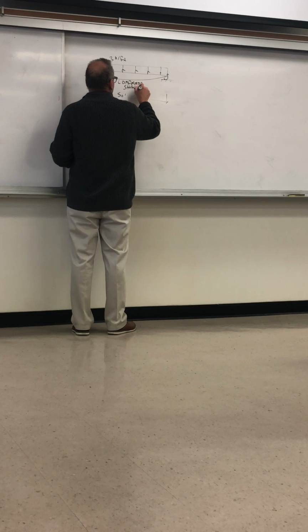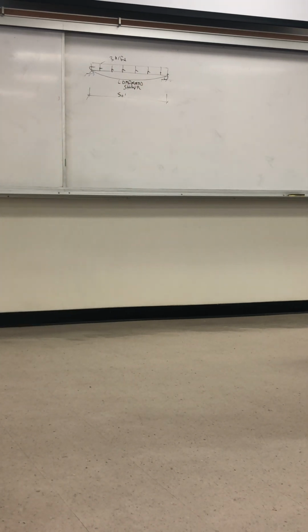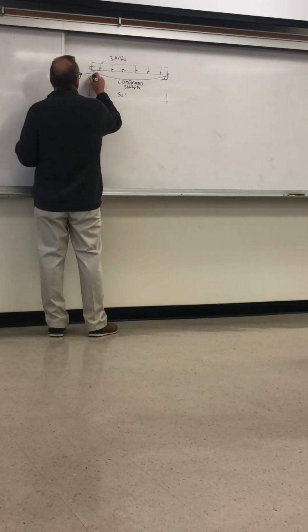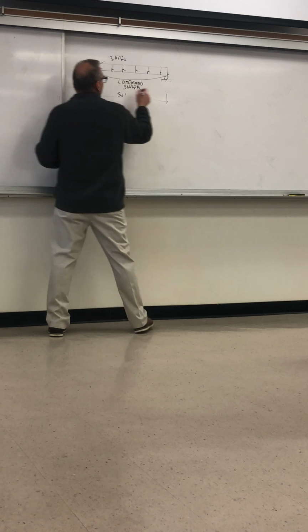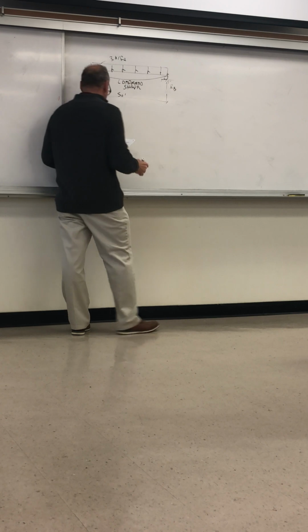Greatly exaggerated, the deformed shape is shown vertically so that you can see it, but the pattern of the displaced shape at the ends is clear. The ends are free to rotate. We have reaction A and reaction B. You can solve those based on statics.